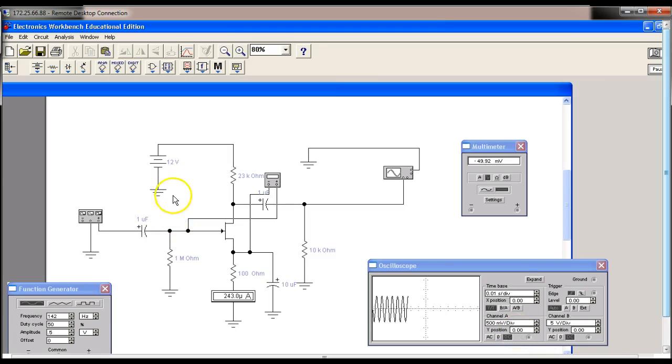So that means on a bipolar transistor, we have to bias it over here on the base. But on a JFET, we bias it usually over here on the source. And we use this resistor to set the input impedance of the amplifier, which is really neat. So these guys here are a little easier to design. Choosing this size resistor is critical. You have to look at the spec sheets and play around with it. But once you got it set up, then it's pretty easy to work with.